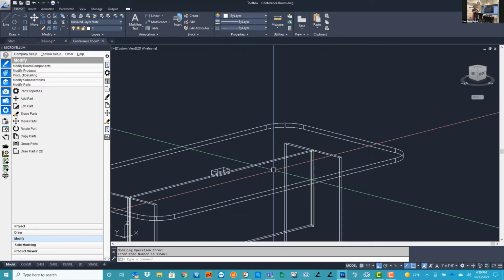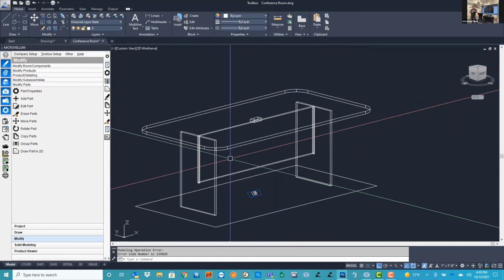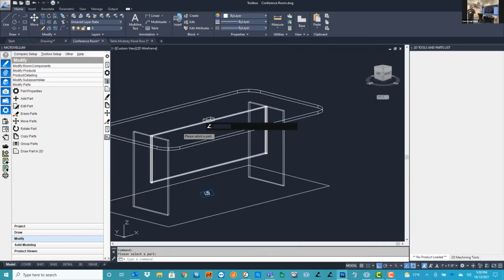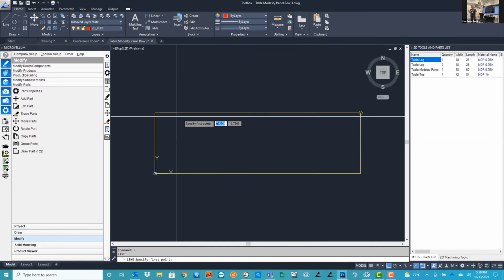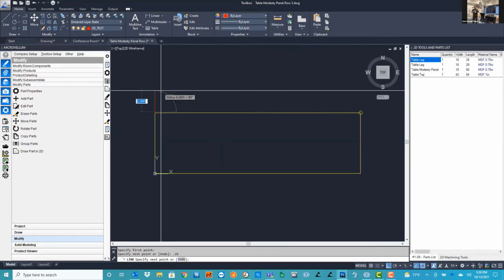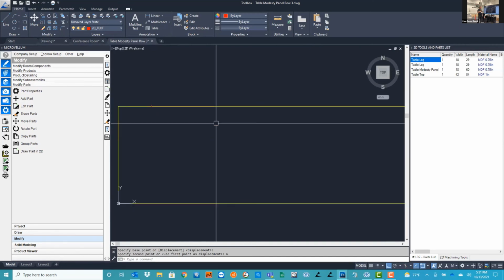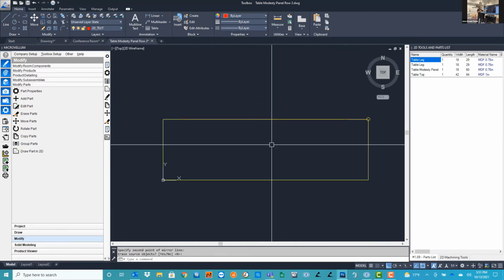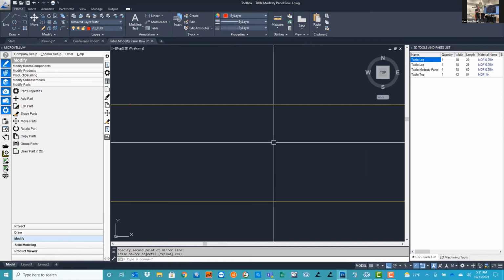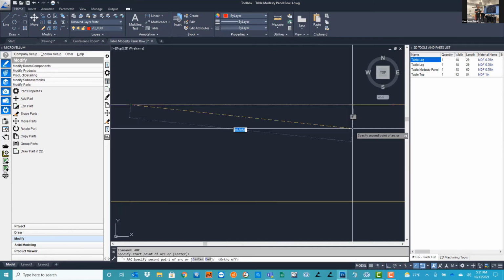I'm going to go back to the 2D part editor one more time. The last time I used a macro, this time I'm just going to draw AutoCAD lines and arcs. I'm just simply drawing in AutoCAD to create a tool path. So I created a lead in, I'm going to mirror it over there and put in a lead out, and then I'm going to create an arc. And this is going to be the path for the machine to run to cut the part.